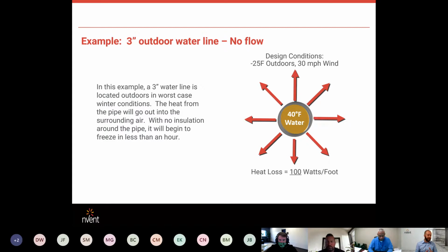And the reason I'm mentioning that is it's not uncommon to get a call or an inquiry where people are discussing heat tracing and they want to heat trace the pipe, but sometimes have no plans on insulating the pipe. We quickly have to correct that, in that there's not really any heat trace that I'm aware of in the industry that can really heat up an application or even guarantee any maintained temperatures without insulation.